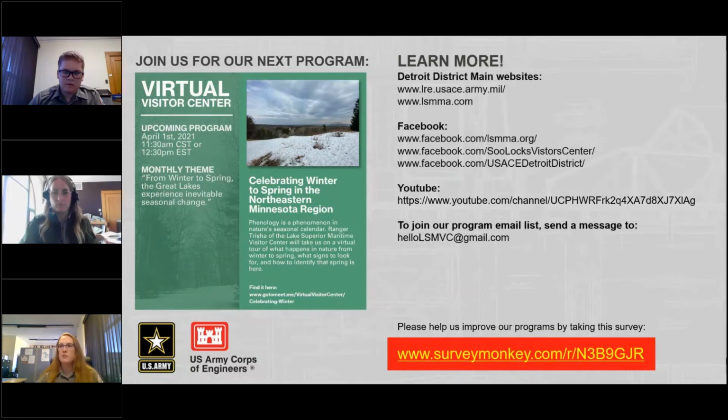So he thought that there's got to be a way to design a vessel that's not going to be this squirrely. And what he came up with was the whalebacks, which basically are kind of like a big cigar that sits most of the way underwater once it's fully loaded. And so during inclement weather, this allowed any storms, any waves or anything just to wash straight over the hull rather than smacking the side of the hull and making the vessel squirrely. So that was the reasoning behind that design.